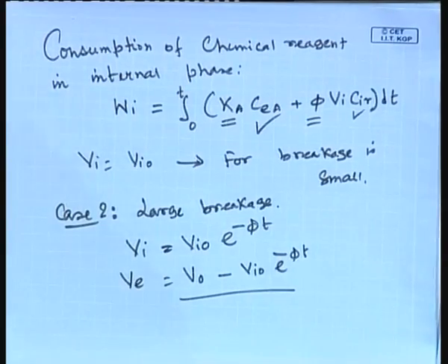If not, then you re-guess the values of the parameters, and how will it be done? It will be done by an optimizer. So, your main subroutine has to be hooked up with an optimizer that will automatically select the next set of parameter values, and it will calculate the profile once again and see whether the sum of the squares is minimum or not. Okay.